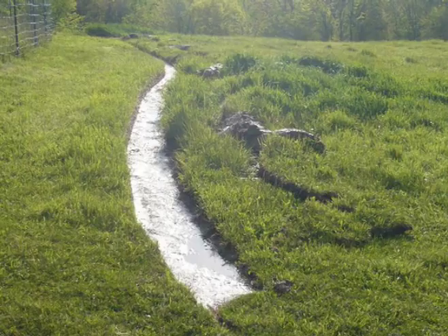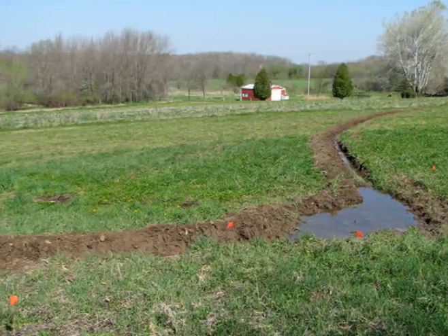Various different ways. I'll show you how. Keep paralleling up. We put a saddle pond when we can. It's outlets, drive-through ponds, and it's ridge ponds, it's ridge outlets. Well, why on earth would you put a pond up on the saddle? You can't have water up there. Well, yeah, you can. You collect it from the hills on either side. So these are collecting the water, storing it here, it fills up and goes back. This water otherwise would have gone and it's gone, but instead it stays on the farm, sheets off of here, and your ridges now become moister, and the valleys become drier. So if you have wet spots on the farm, many people say, oh, drain this for me. It's like, no, let's prevent the water from getting there in the first place and see what it does.